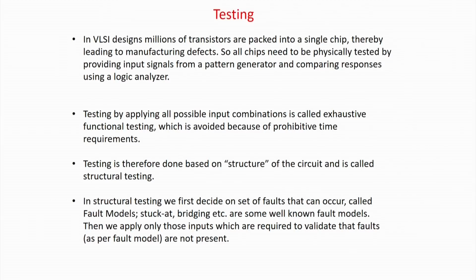Now testing. Already I have told you in VLSI design, millions of transistors are packed into a single chip, so they have a lot of manufacturing defects. So the yield is not very high, not 99% plus, which is generally the case for traditional engineering devices like an electric fan and iron. We all know how to design a fan and iron. Once you design it, there is 99.9% surety they will do their functionality. So their testing is not that important.